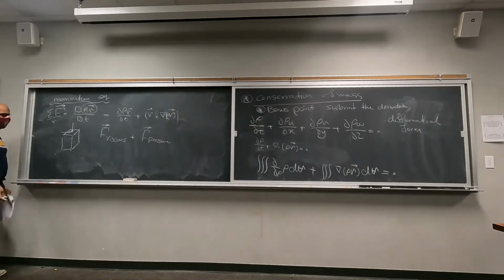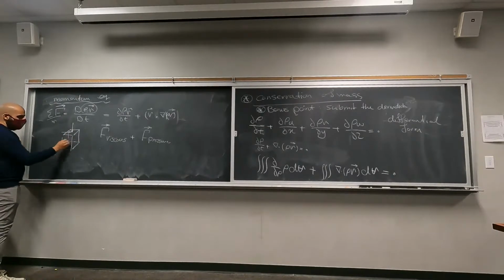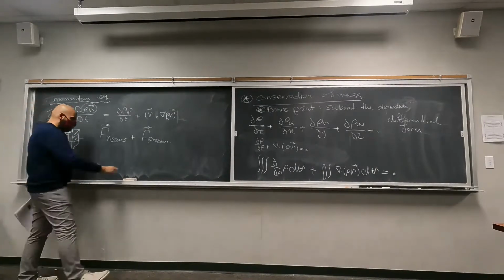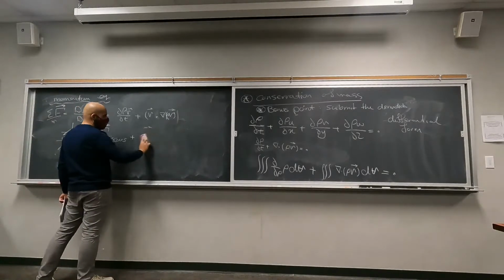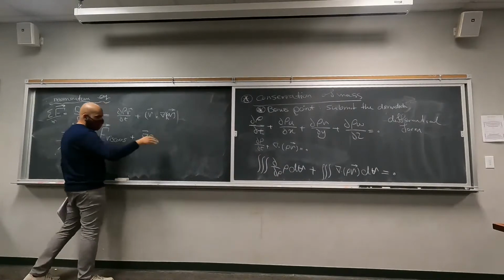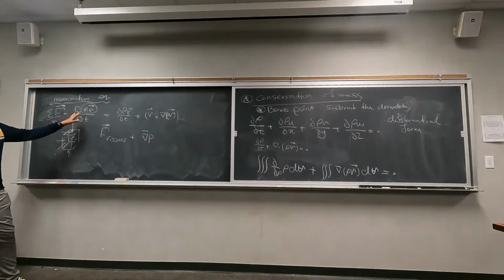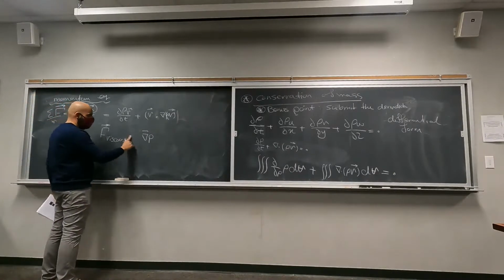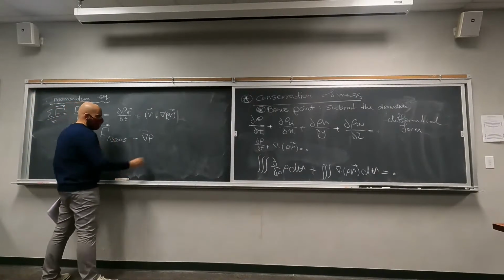Pressure forces are essentially going to be canceled out in all of these different directions if there is no pressure gradient. So if you simplify things, you will essentially end up with pressure gradient multiplied by the volume, but we have divided everything by the volume before, so we're just going to stick with the pressure gradient, and this is actually the negative pressure gradient.